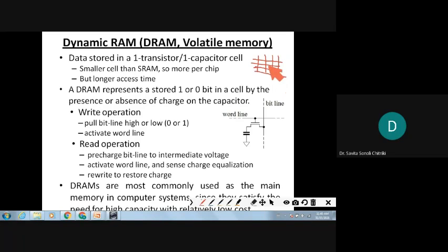At the intersection of row and column, what will be there? You can think of it as a switch, in ROMs. Whichever cell you want to retain as 1, the switch will be connected. If you don't want this cell to be stored as 1, then the switch has to be blown off. Later you cannot connect.